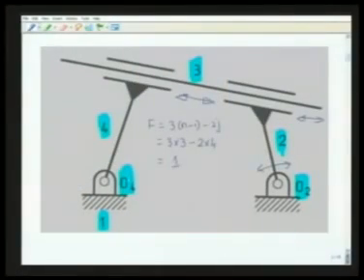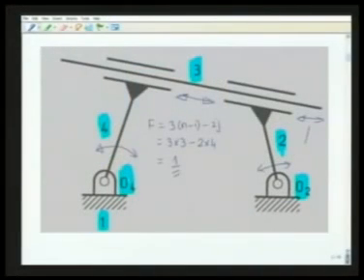However, link 2 or link 4 cannot be moved at all. This is permanently locked. So this acts like a structure. Then what is this degree of freedom 1? That is nothing but this redundant degree of freedom of the link 3 along this direction of the prismatic pairs.